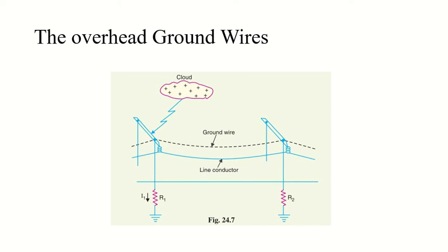Now we were discussing that the degree of the protection which is provided by the ground wire depends upon the footing resistance of the tower as well. How much value does it hold, right? What value of footing resistance of the tower is. Let's say, for example, the tower footing resistance is R1 ohms, and the lightning current from the tower to the ground is I1 amperes. Then the tower rises to the potential of V1, and this V1 will be equal to I1 into R1.